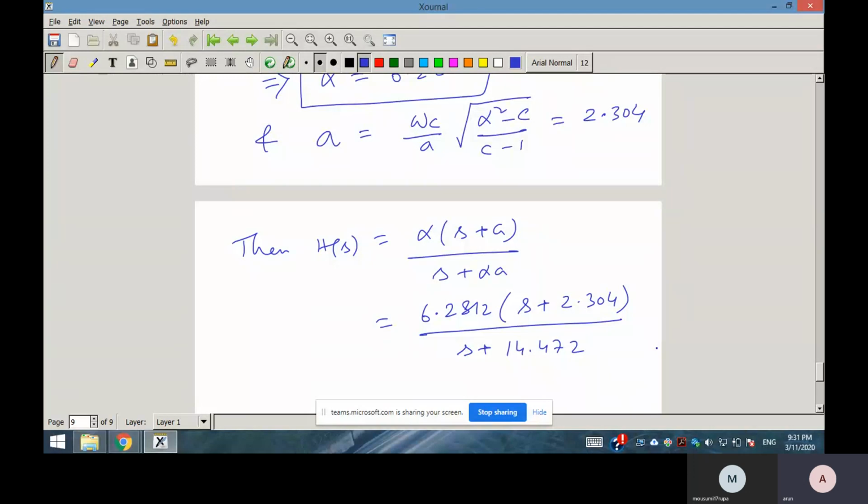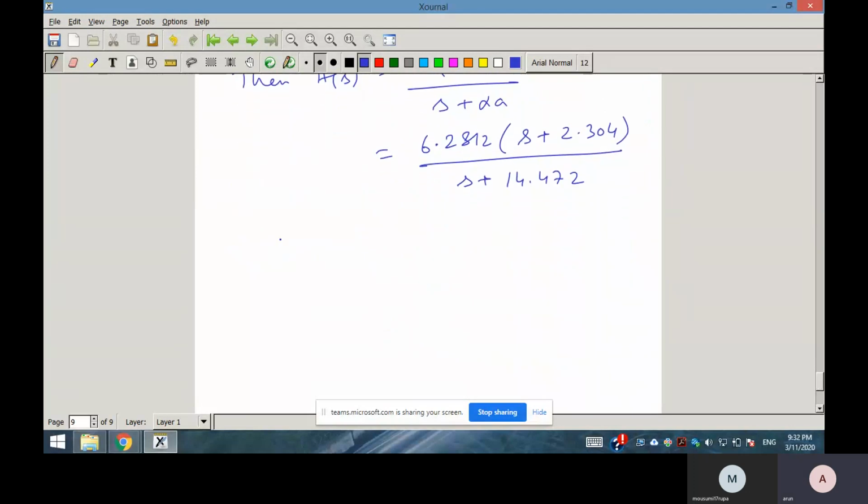Now the question is how to realize the controller in an analog fashion. Suppose we have been given a problem, and we have determined A and alpha. So how to implement this transfer function? You can implement it digitally, and nowadays all controllers are implemented digitally, but still the beauty of these lag-lead controllers or simple controllers like this is that they can be realized or implemented in an analog fashion easily. So this is one implementation diagram.